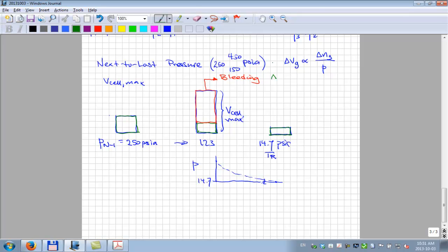So we will finally get, in a sense, some estimate, but there's some uncertainty here. You'll get moles removed. Of course, the final volume removed is now a standard gas volume, so they're basically one and the same because the volume is at standard conditions at the last stage, right? You'll get the molecular weight of the gas, and so forth. There'll be some more uncertainty to this because it's not really an equilibrium process. And then you'll end up with this residual oil. And this is what we call residual oil.